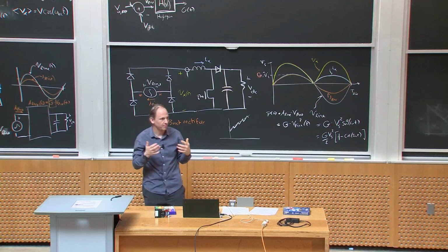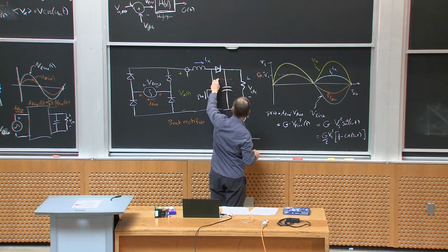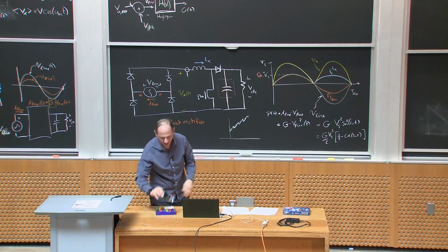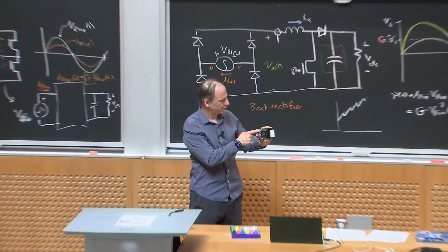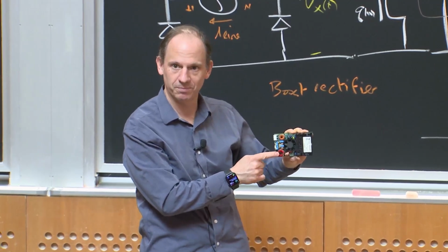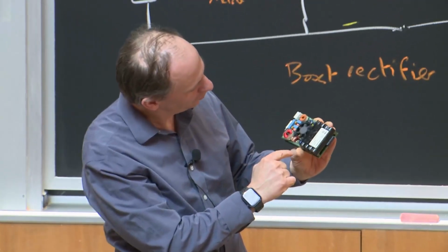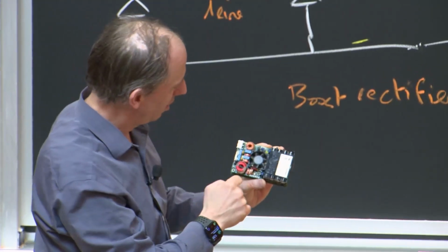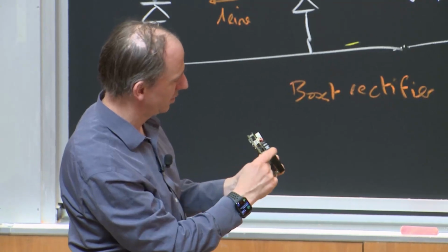And in fact, we're going to talk about that in a minute. The size of this capacitor right here tends to be a very dominant thing in most PFC rectifiers, okay? Just to illustrate that, I've got one with me here. This part on your very left is basically the line filter, right? Because we're switching and I gotta keep the PWM junk out of the line. Has a fan. Then you'll see, if you look carefully, you see these 4 diodes here, 1, 2, 3, 4, those are the 4 diodes. The inductor is a little bit hard to see because it's buried in here.